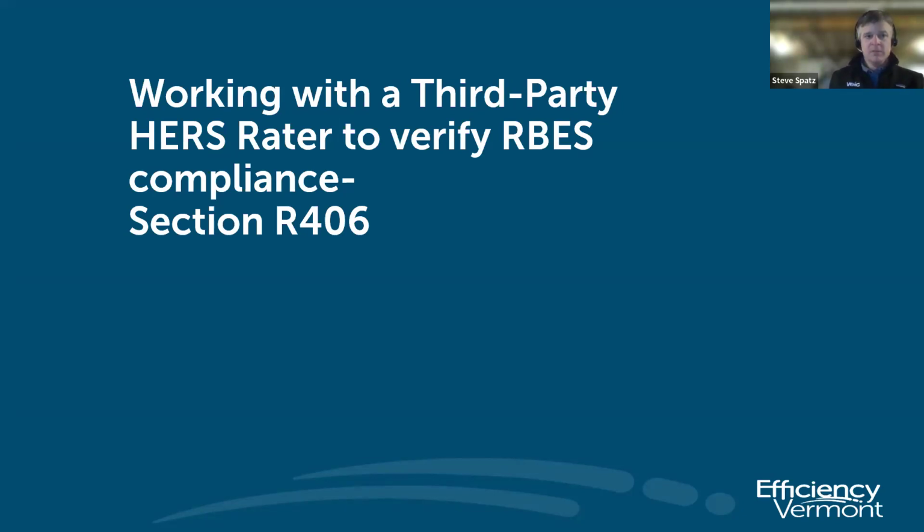A HERS rating, and using the ERI approach, accounts for the efficiency of the mechanical equipment, and the more efficient the mechanical equipment and any use of renewables, et cetera, has a big impact on the HERS score and your compliance. So the odd duck out here is ResCheck, which, as I've noted, is only taking into account the building envelope performance, the shell performance. So I think that really is the factor of why ResCheck is defined as not being an option for stretch code.